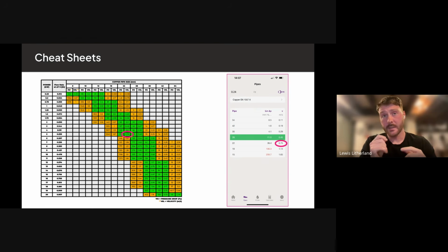One thing I wanted to point out is that it's 76 here, but there's that 0.75. It took us 10 minutes to talk through and work out. You literally say, well, it's 5 kilowatts. If you remember that load going down the left-hand side, and then we did all them calculations to find out. If you looked at this chart and you went to 5 kilowatts, you go across and it's 22 mil, I'd say it was 0.75 or 76 in this case of meters per second. There's your velocity straight away. How much time that saved you. But again, so important to understand where that comes from.